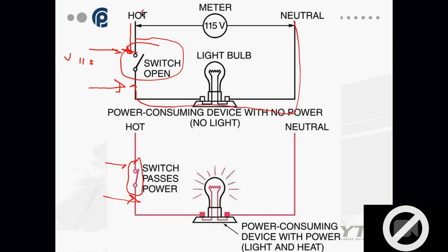Now let's say I disconnected the circuit from electrical. In other words, I no longer have power on the circuit because we cannot take a resistance reading with power on the circuit. If I take my resistance reading, and someone kept saying this earlier, so now say it. What is my resistance across an open switch?